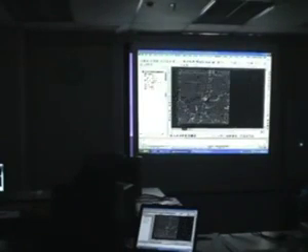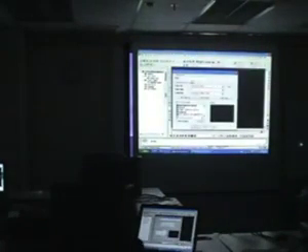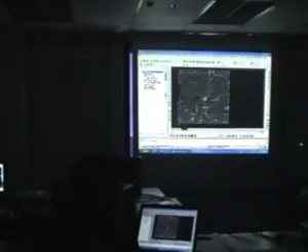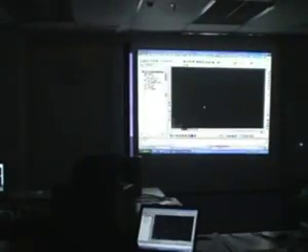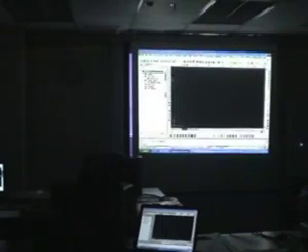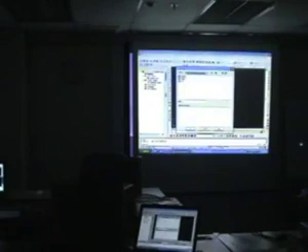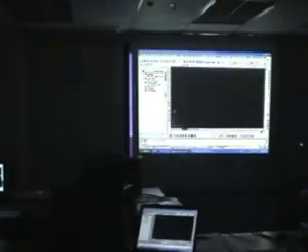So we can't do the conversion directly from this drawing. What I'm going to do is create a new drawing. I'm just going to call this points. So now we've got a new drawing, and what we need to do is attach the drawing which we saw just now. This is the use of the workspace on the left side. Under drawings, I'm going to attach 2D points. You can see 2D points here.